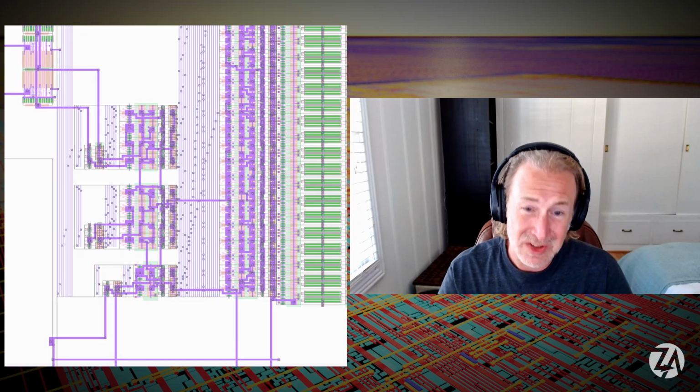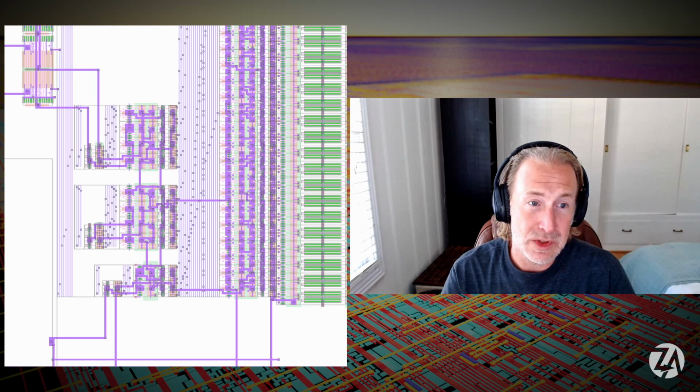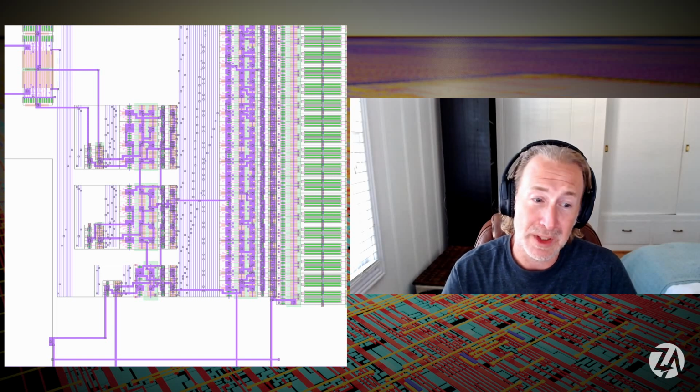Yeah, exactly. The Bitcell is a 6-transistor cell, which is roughly one fifth the size of a flip-flop. Even when you add the extra decode logic and so on, you still get area savings anywhere above a couple hundred flip-flops, or 100 bits. So it makes sense to use these whenever you use memories.